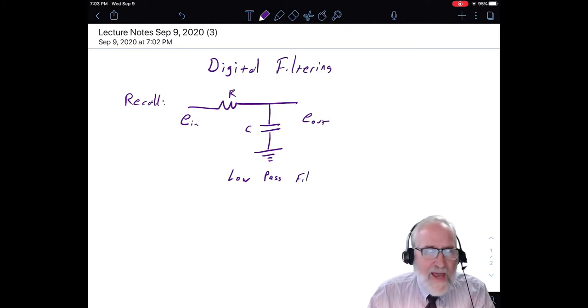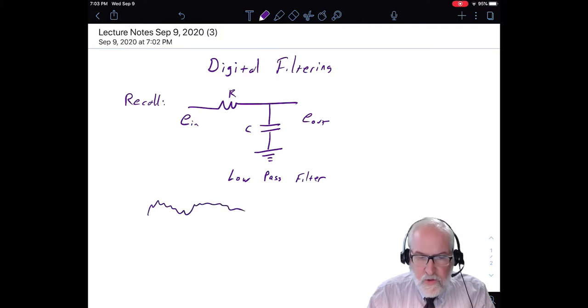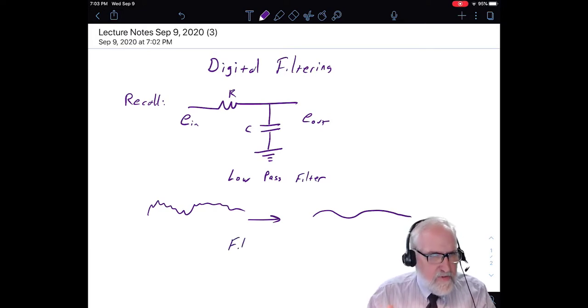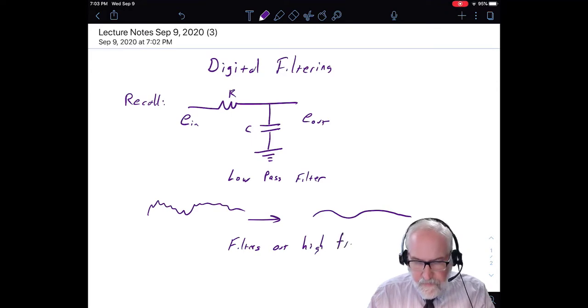It's called a low pass filter because it passes the low frequency component of our signal, and that's usually where the information is. Often a signal is noisy because it's the high frequency noise that contaminates it. That's not always the case, but for the vast majority of, say, mechanical engineering applications, we'll see something that a low pass filter can be used to clean up.